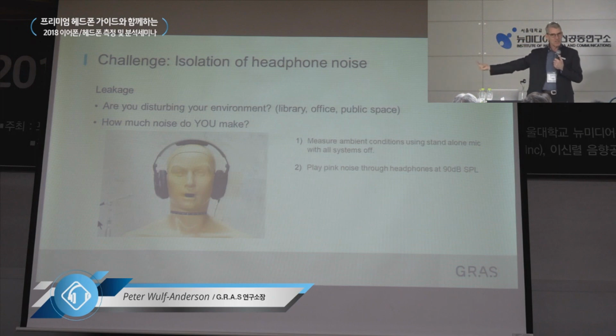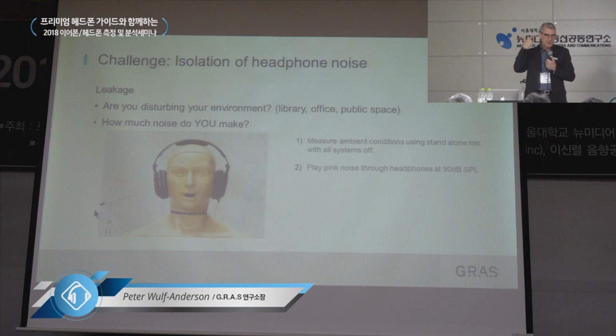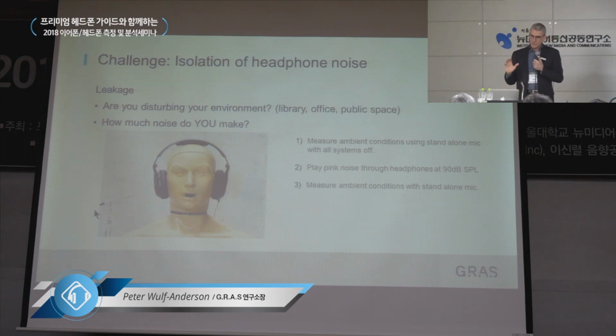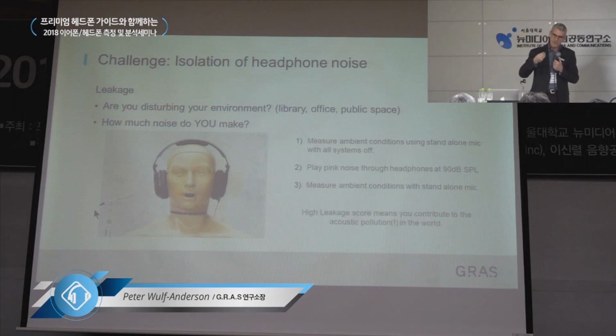And then again, measure with the same microphone how much of the noise you play in the headphones is actually leaking to the outside. So now you have the noise pollution that your headphone generates, and then you can decide whether it is too much or whether it's an okay level that can be accepted by the people around you.